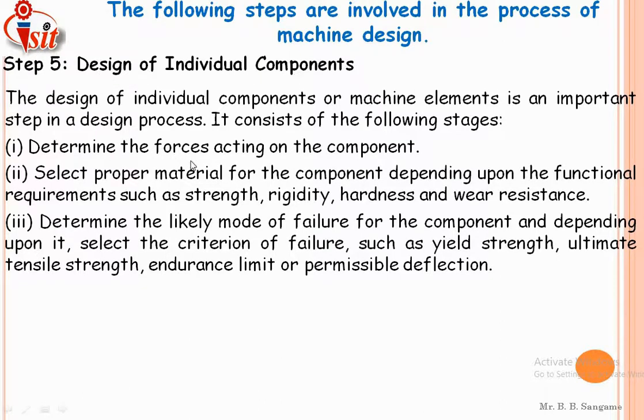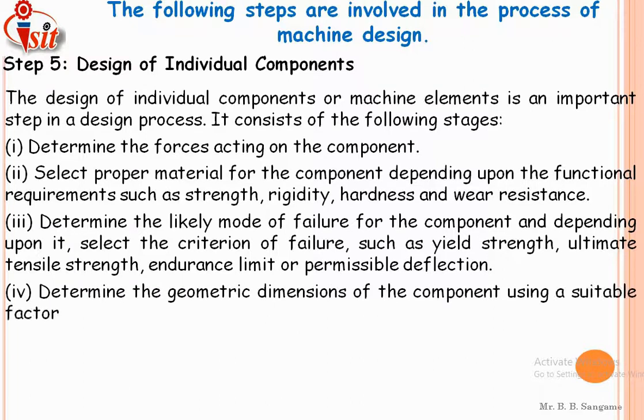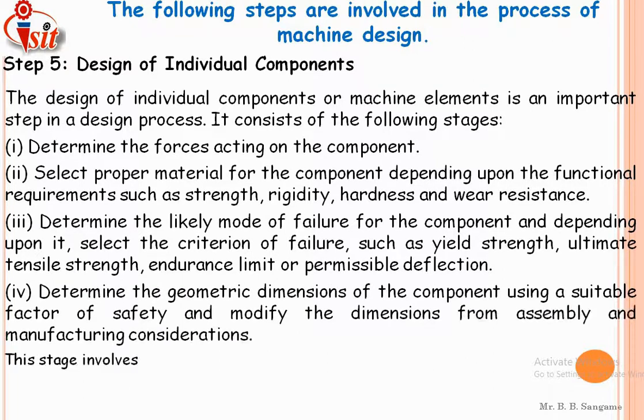That is, determine the forces acting on the component, select the proper material depending on the functional requirement, and determine the likely mode of failure of the component due to the induction of the stresses. The next part is to determine the geometric dimensions of the component using a suitable factor of safety.